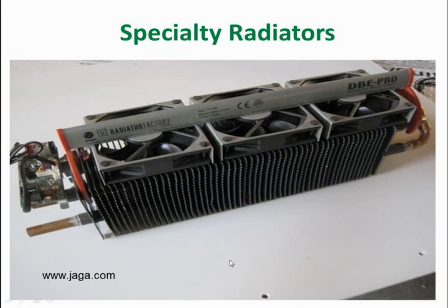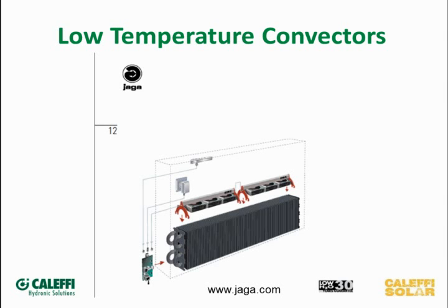So if that's something that you're looking at, and this is a good product if you're going to do a retrofit or remodel where they don't have the ability to put in a concrete slab, they still want to go with some kind of hydronic-based system, they would be able to run that with a geo or maybe have a solar component to that, then this would be a good emitter to look at. Now there's other companies that do that. I'm not just trying to spiel a certain brand here.